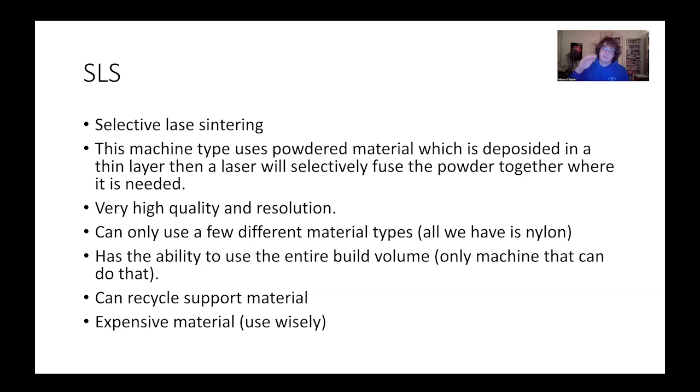Another helpful aspect of having the powder be its own support is that you can utilize the full build volume. Okay. Having the entire volume already filled with this powder means you have very reliable support. You never really want to, on an FDM machine, stack parts on top of each other and utilize the full build volume. You're likely to run into failures in terms of not being able to support, or under-extrusion or something like that. But this lets you use the entire build volume, which makes it really fast if you're a student worker in the Ideas Hub to just set up a bunch of prints and have everything run on a daily or twice daily basis, depending on how many you can fit in there. Okay. The material is quite expensive, even though you can recycle it. So yeah, you should use it wisely.